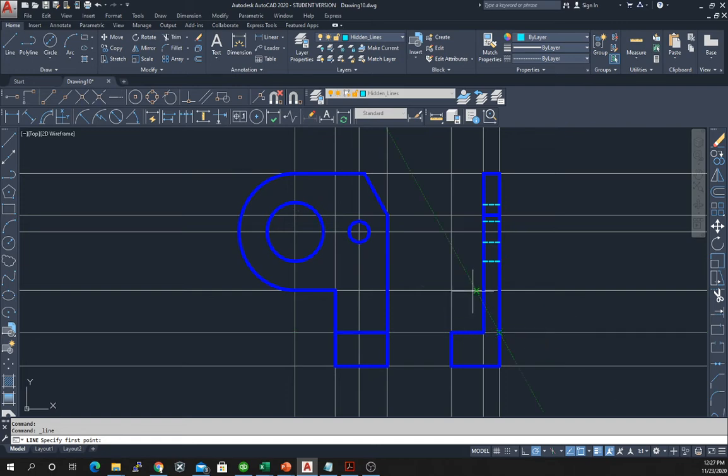At this point, to transfer this over. The reason we have to show a hidden line over here is because of this change right here. We don't show one at the top because there's nothing to show. You actually have a cut there anyway. Okay, so that takes care of that portion of the drawing.